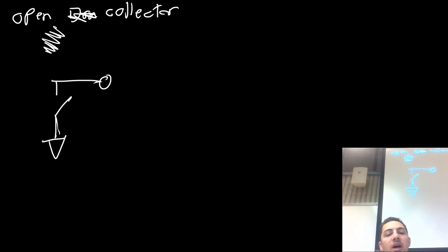What does that mean for us? Well, it means if we close the switch, we definitely see 0 volts. If we open the switch, what do we see? Where is 5 volts anywhere on this page? Nope. 0 volts isn't connected. It's open. So there's no connection anywhere. The magic word I'm looking for here starts with an F. Floating.